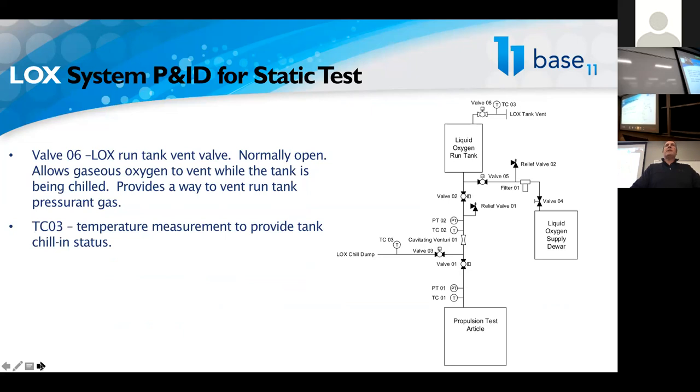There are ways to measure liquid levels in cryo tanks. One way could be head pressure. You can look at the differential between the pressure in the top and the bottom, and if it's a closed system, the only difference is going to be the weight of the liquid in the tank. So head pressure is typically what's used to measure the volume in bulk tanks. There's floats, there's ultrasonic sensors, there's all kinds of different ways of doing it. But for low cost, relatively high pressure systems, there's not a really good, simple solution. And so simply overflowing the tank is the cheapest and easiest way to know that your LOX tank is full.